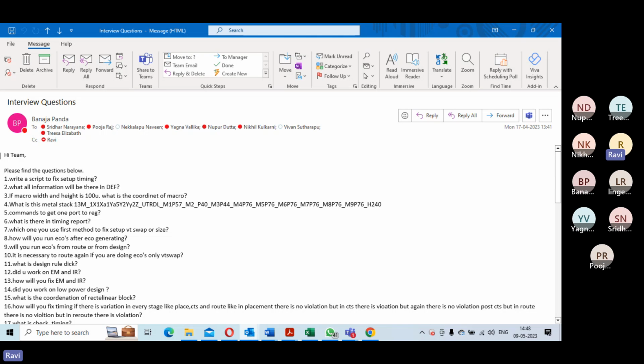Okay, it will improve your timing. It will give you betterment on the timing. But the counter to it is, your leakage may go up, but that is okay. Because anyway, your sizing is going to increase your power consumption. But principally, whatever fixes you do, you will more or less concentrate not to create DRCs.